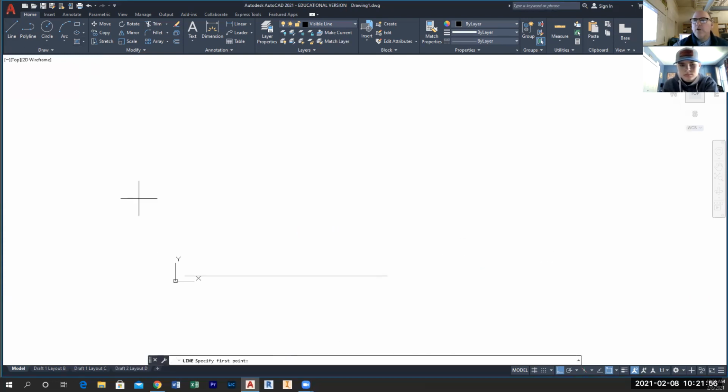And then I'm gonna go ahead and draw a vertical line, and I can go right off the end of that too. And that has to be the height of 1.5 plus an inch, maybe 1.5 inches between views, plus 2. So that's 1, 2, 3, 4. I'm going to say 5, 6 inches. As long as it's about that high, 7 inches, that's good. I'm going to do a vertical line and a horizontal line. What I end up doing then is just going ahead and offsetting. My height is 1.5. Let's go offset.